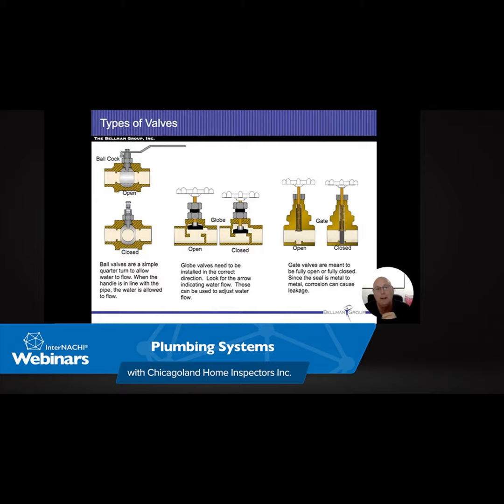And just for anybody else, let me pop up what Mark put on here. He was saying that he thinks there's an error with the friction loss with the size of the pipe, and that may be true. I'm never afraid to make up a number just to prove a point. I'm not worried about being accurate on the length and the friction loss. The point I was trying to make is that whether you go from a small pipe to a big pipe, the amount of friction loss is still going to be the same at the end result. It doesn't matter the order of the flow.